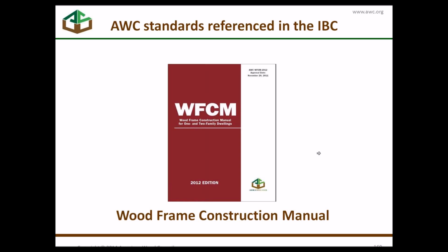The scope of buildings that can use the wood frame construction manual is limited, but that is broadening slightly with the 2015 IBC. There will be a little bit more use for the wood frame construction manual in commercial structures as long as they fit within the scope of the document for loads, building geometry, height, and so forth. So those are the main reference documents in terms of standards from the American Wood Council.